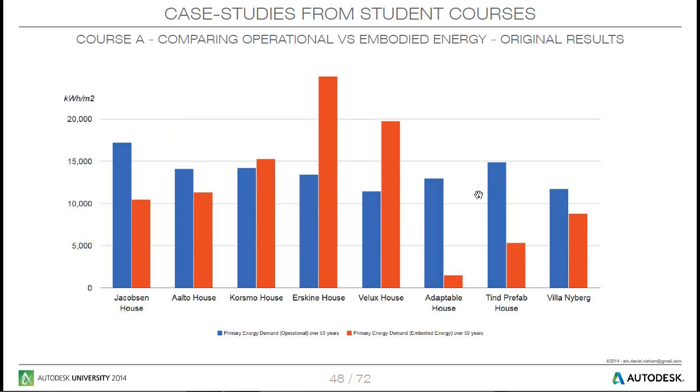And that's also some of the limitation with the energy simulation, if you're talking about glazing. The glazing you can choose in Revit is quite limited, so I had to make my own glazing properties. And that's a little bit tricky, but it's possible.